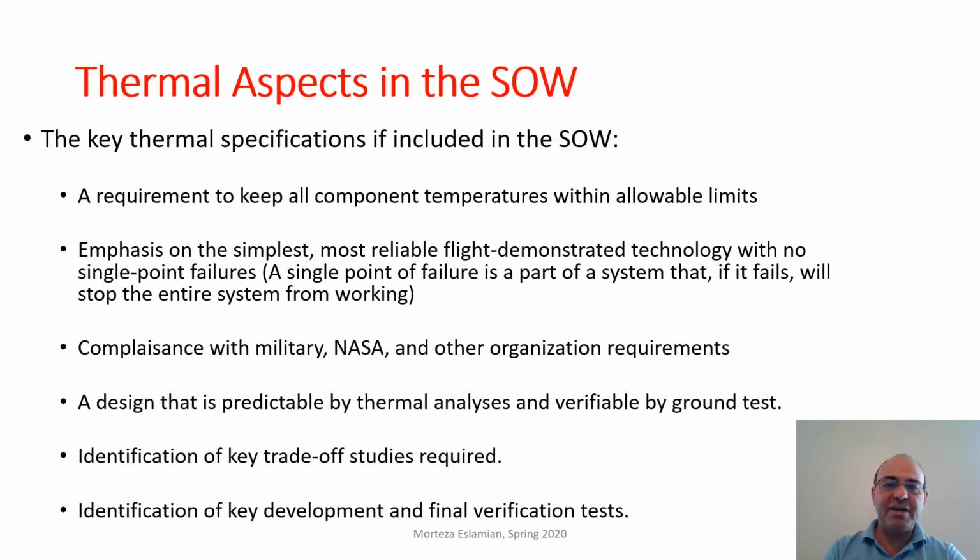So the thermal aspects in the statement of work include the following. A requirement to keep all component temperatures within the allowable limits. This is kind of obvious. This is the requirement that all equipment must operate within the allowable limits. Emphasis on the simplest, most reliable, flight-demonstrated technology. So high TRL, the technology readiness level that we talked about.